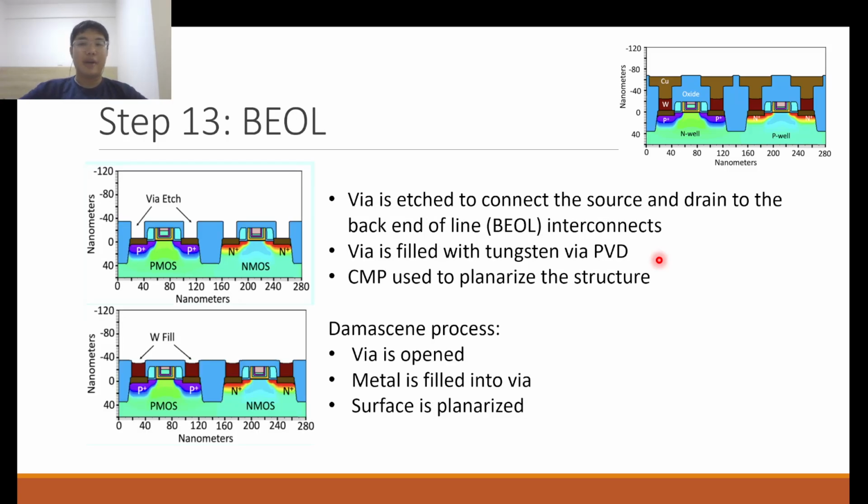And okay, finally we can begin on what's called the back end of line, which is BEOL. So our device, which is our transistor, is finished. So you can think of all the semiconductor related processes as being kind of done. And what is left is connecting the device to the back end of the chip. If you've seen the computer chip before, you have all your studs that basically connect to your eventual PCB and your eventual motherboard and things like that. So it's time to connect the device to the back side of the chip.